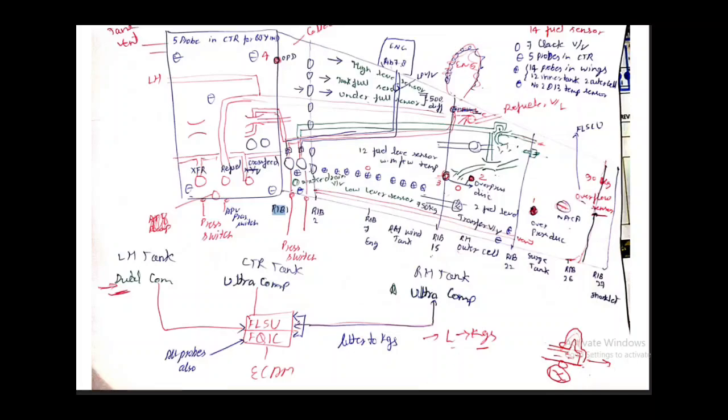But once your aircraft is in flight and banking, what happens? This clack valve will close, and this will prevent the fuel from going out of this wing area to the other area, meaning the outer and inner cell. So once the aircraft is banking, the pump will have, in that compartment between rib 1 and rib 2, sufficient fuel to supply the engine, positive flow to the engine. So that's why this clack valve is there.